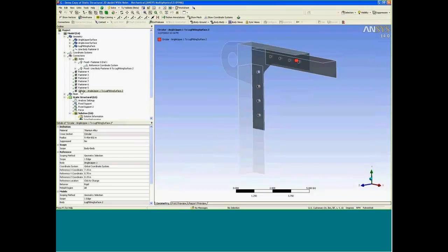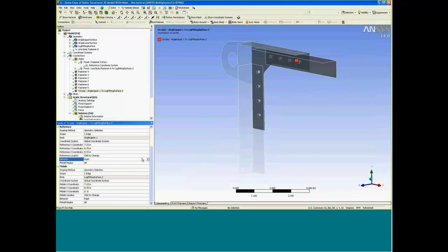Again, with the beam connection, you can also utilize rigid and/or flexible and deformable behavior at the attachments. And again, I'd tend towards using deformable to allow those shell elements to deform as they may under load.